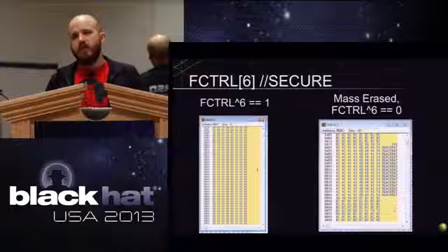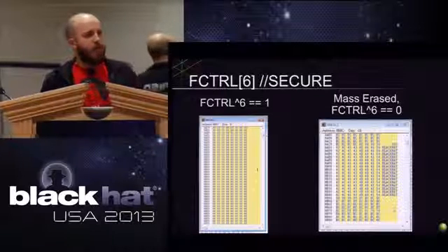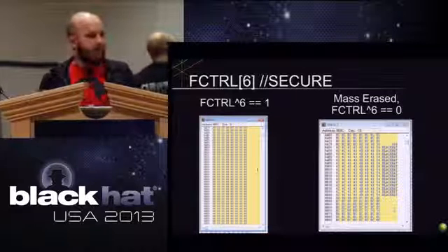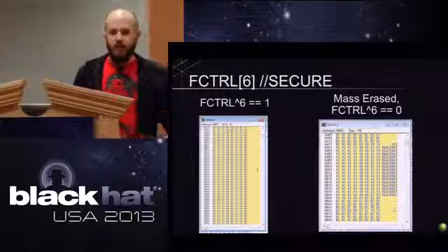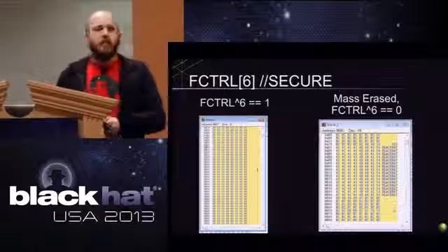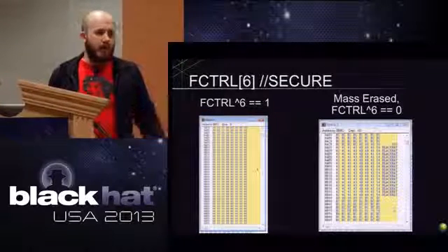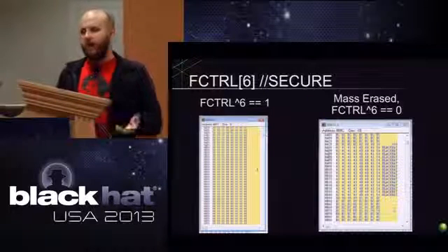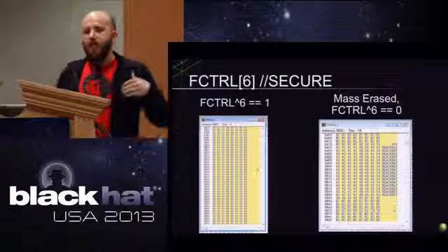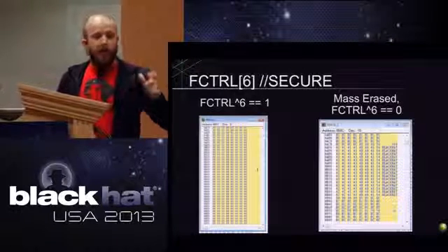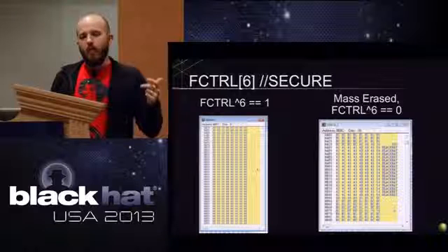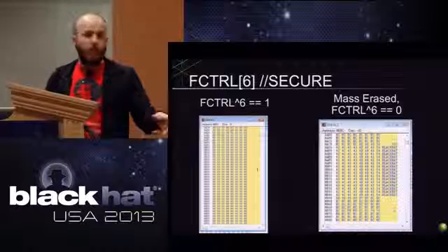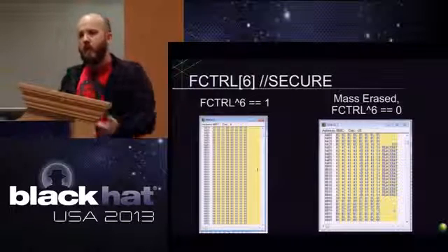So, this is like being able to see RAM without being able to see the code. You don't necessarily have any context to know what these things are, outside of knowing what the device does. So let's say it's a smart meter, and let's say that it's doing encryption as part of an ANSI standard. Well, you know certain things about how that's going to work. You know what type of encryption it uses, what its key sizes are, things like that. And coincidentally, the way that's implemented in code will most commonly require you to copy that key out of code memory into RAM to then perform operations on it.